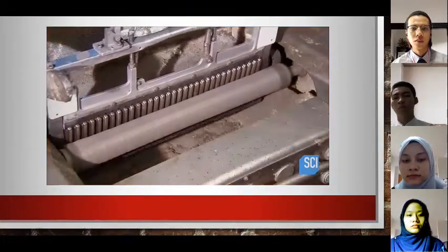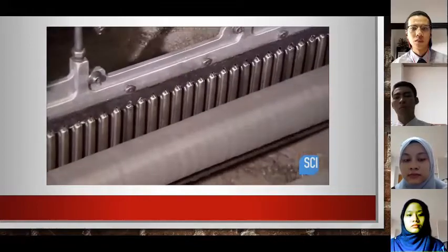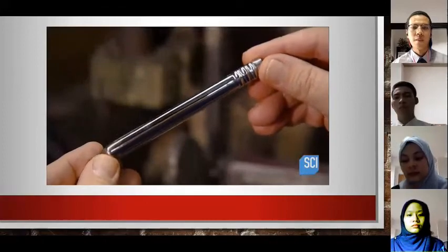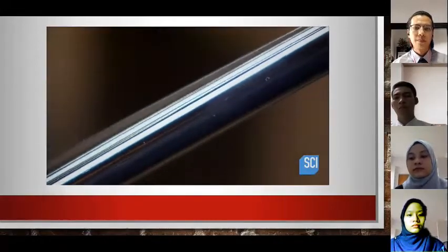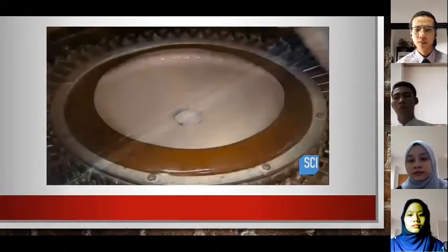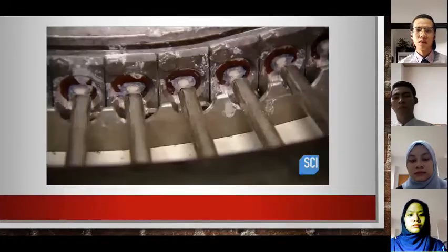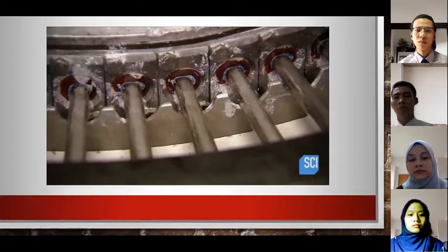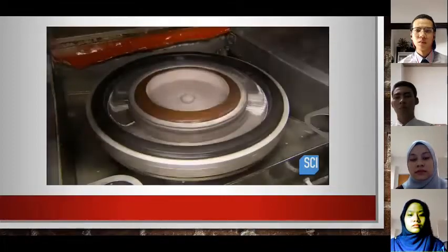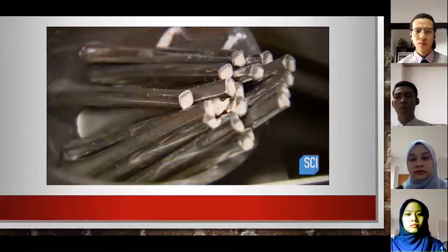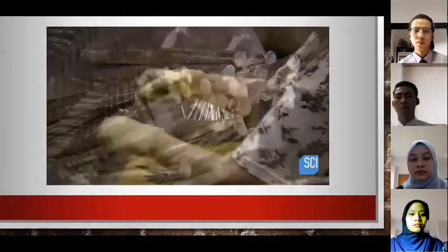An edging machine grinds the solder line until it blends in with the surrounding stainless steel. Workers pour liquid cement into the center of a carousel on which they mount 50 handles at a time. As the carousel spins, the centrifugal force shoots the cement outward, filling the handle cavities.